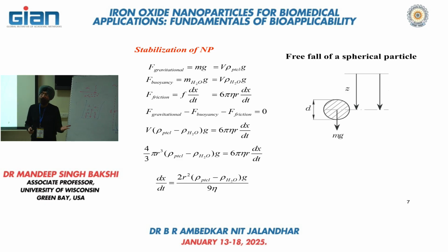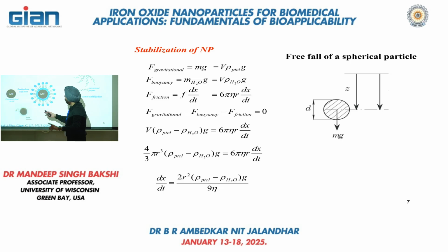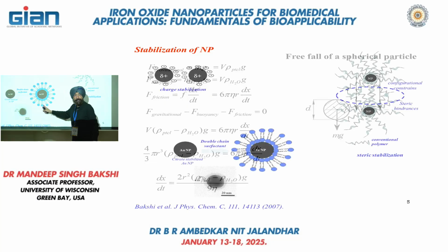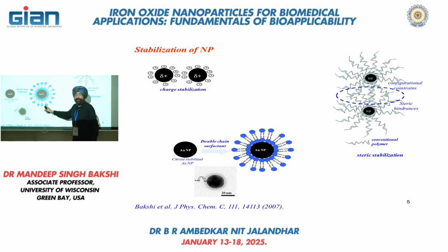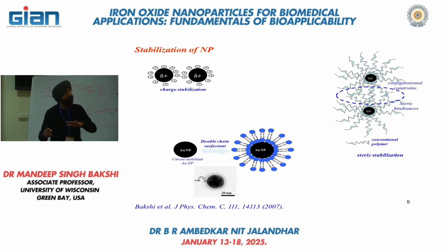We know what is the viscosity. But how the viscous drag can be imposed, that is what here I have explained. For the viscous drag, we talk about the electrical double layer. The stronger the electrical double layer or the surfactant which we are going to use, the stronger are the electrostatic interactions with the water molecule, and that is enhancing the viscous drag or the frictional forces, and they are opposing the settlement of the particle.